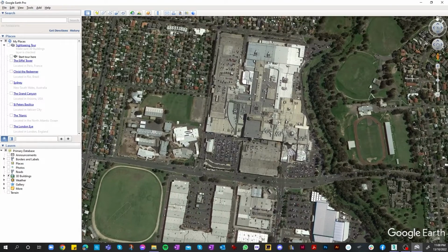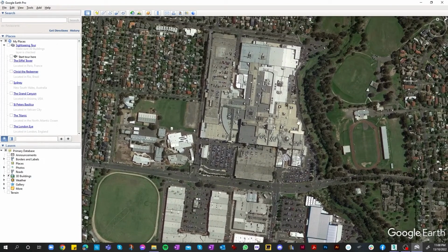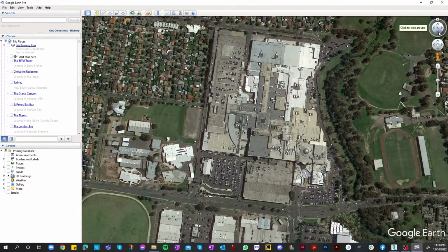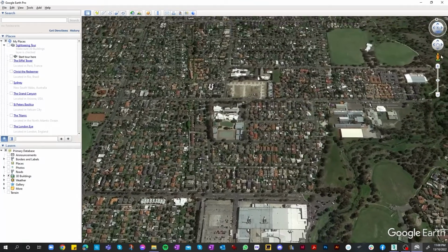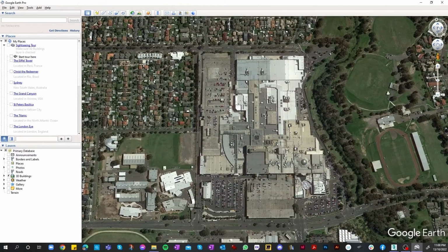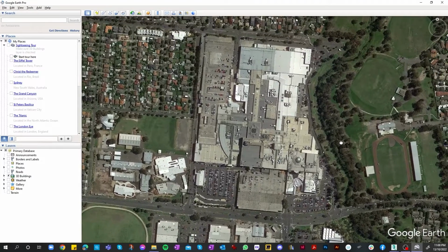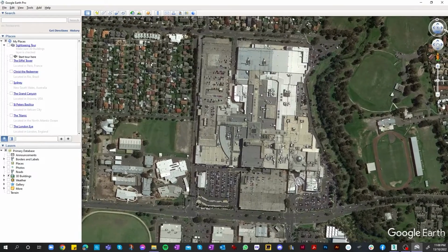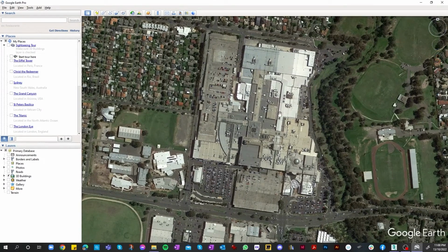So first of all, we need to make sure our view is set straight. Using the eye tool here, make sure it's completely bird's eye by just panning with the down tool. And then to set it to true north, we just click on the N until it's automatically set. And then from there, what we need to do is first get our historical imagery up.